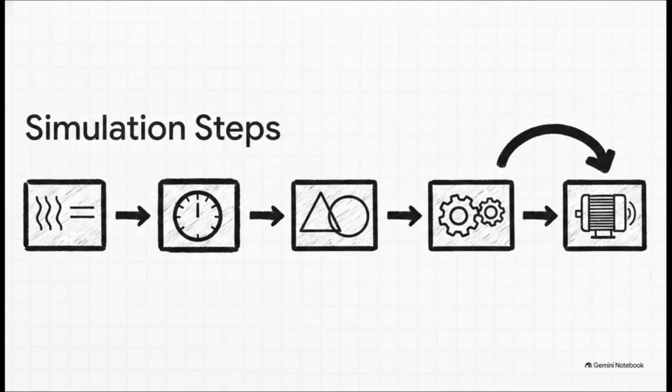Now, to simulate this successfully, you're going to want to follow these specific steps. First, implement those transformation blocks. Second, build out your reference frame selector so you can actually choose your rotation speed. Third, you need to accurately program the state space model derivatives for your current and flux. Fourth, use those states to calculate the electromagnetic torque. And fifth, implement the equation of motion to get your rotor speed, making sure to feed that back into the system. If you map these dynamic equations accurately, your virtual machine will spin for sure.